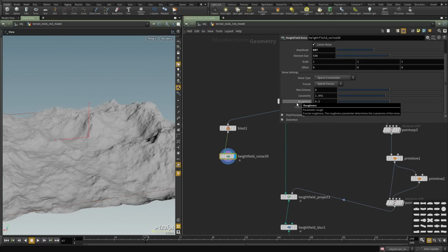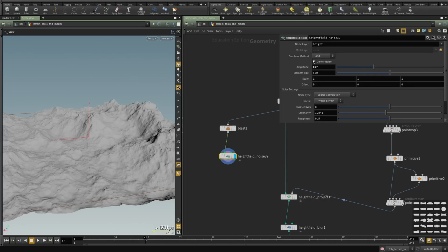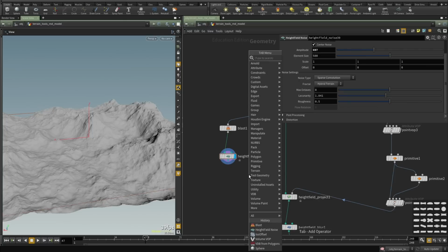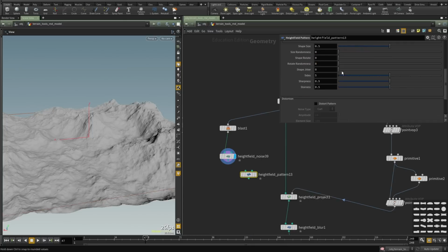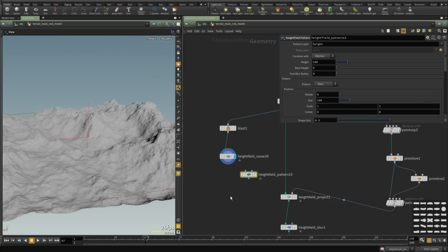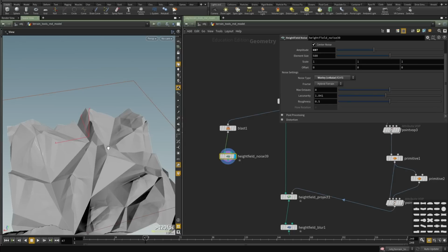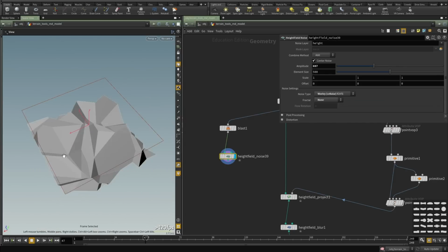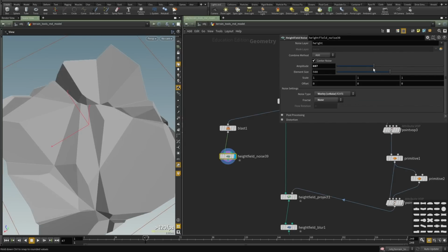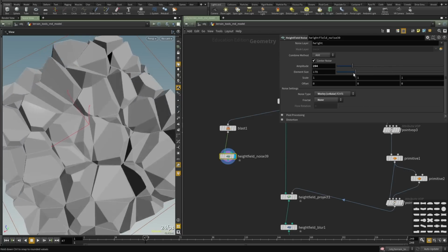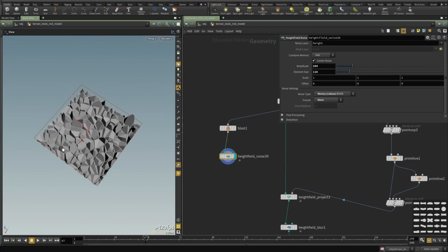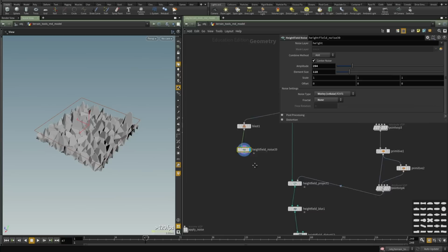But I don't want just this. I want to have access to all the Houdini volume VOPs. I don't want to be limited to this unified noise pattern node. And then the other thing we have is the pattern, which is this. This is great, but again, I don't want to be limited to that. I don't want to stay at this level. Let's say, for example, I put down a Worley noise like this, but I want to change the size of the Worley cells to have a specific size per area. Let's say I want to change the size here to be something else here and something else here. I don't have any of that control.